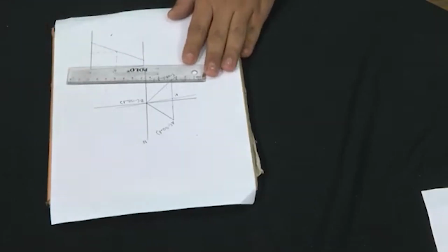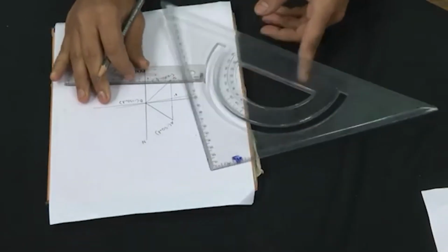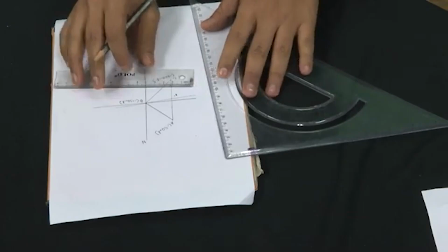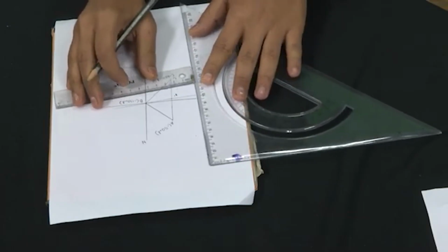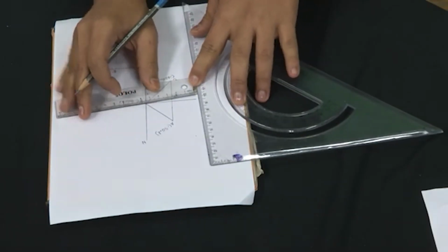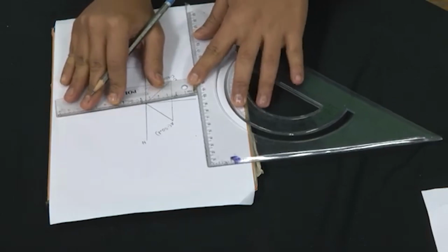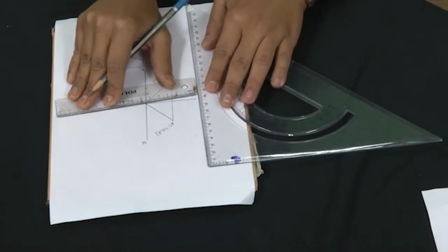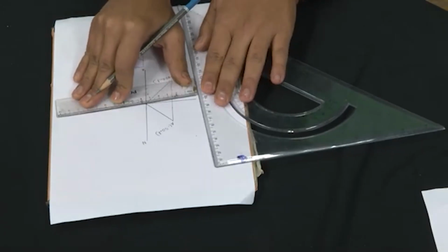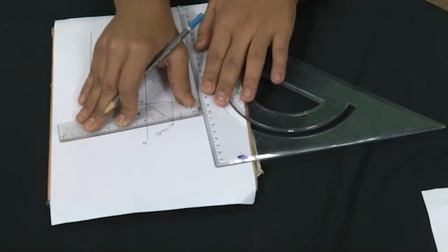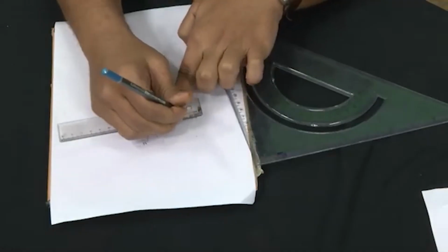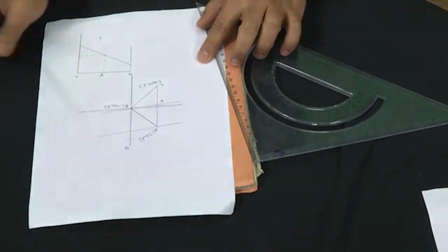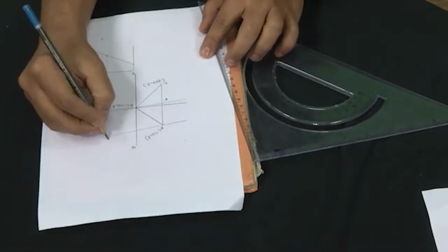Now in this problem I construct a strike line parallel to the minus 130 meter strike line from the point A, which will correspond to the minus 50 meter strike line. So, I name it A dash.